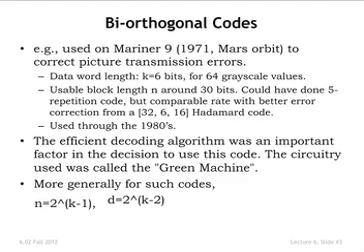So for instance, on Mariner 9, it's 1971. This went into Mars orbit, and the code was used to encode the picture transmissions. Each data word was 6 bits to encode 64 gray levels in a picture. It turned out that because of transmission issues, the safe number of bits for a block was 30 bits.